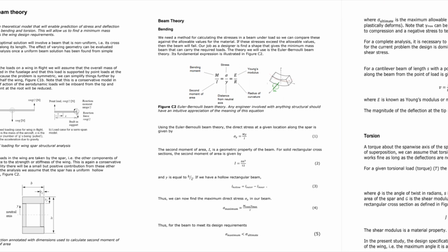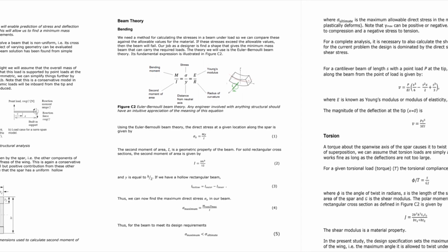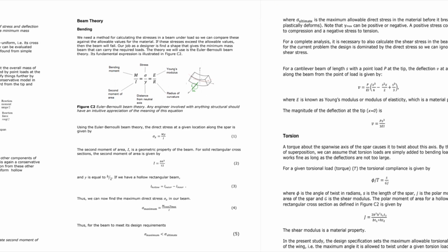In order to get the analysis working, we first studied the documents provided and applied the formulas of the beam theory in Excel for it to calculate and generate outcomes for the bending moments, direct stress, as well as the torsion compliance for the spar.